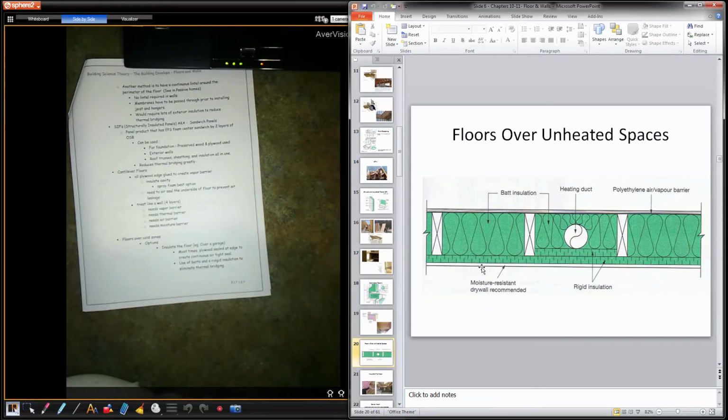So the air sealing across the bottom has to be bang on for the rest of the systems not to fail. You can see adding extra foam below a duct. As soon as you put a duct in place, you start compressing the insulation. So again, whoever's insulating, you want to make sure that you're doing a good job here. If you compress the insulation in this area, that insulation is not doing anything, therefore there's lots of heat loss there. So these cavities are probably better suited for spray foam.